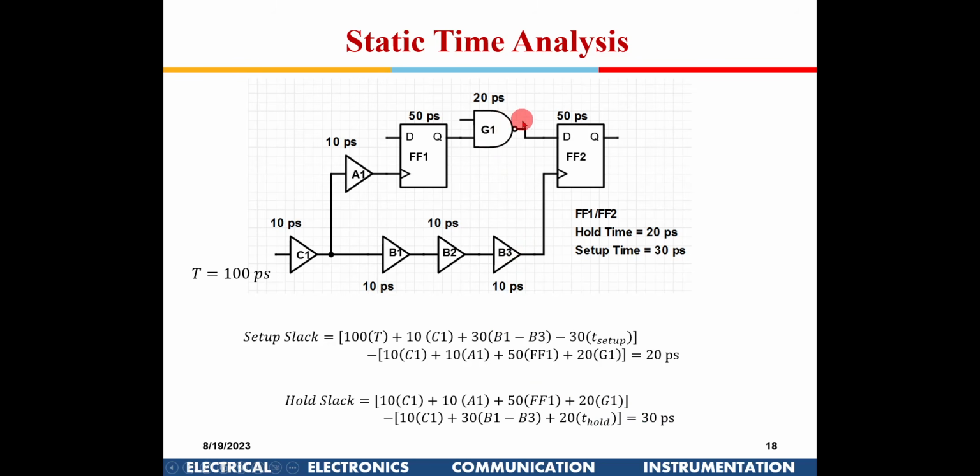So meanwhile, the data should not change. So I take this data out here, right? So it is 10 plus 10 plus 50 plus 20. So this is 30 picosecond. So there is no violation. So this circuit is good, fine, right?